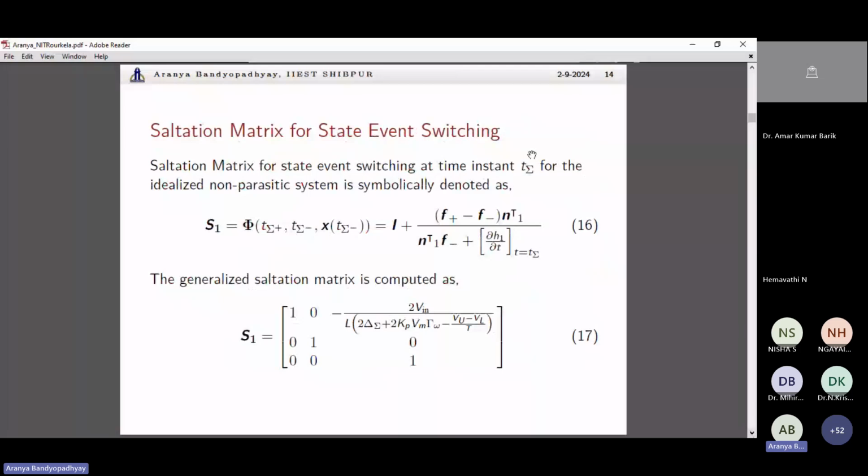Okay, but the problem that inherently arises is that when the periodic orbit has to go through a switching phenomenon, therein lies the problem. What we do is give a perturbation to the original periodic orbit and see how the perturbed trajectory evolves, or how the perturbation itself evolves. We can see how the perturbation evolves through the linear time invariant subsystems when the switch is operating in either mode A or mode B, right?